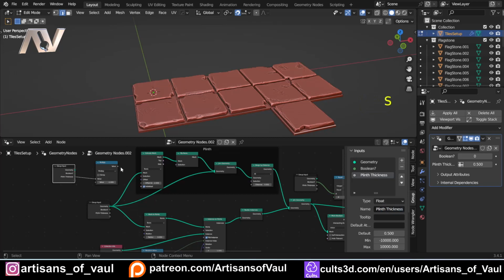So we've got that there, drag that into our offset, and at the moment it's down as 0.5. I'm going to change the default to 1, the minimum as 1. Actually, let's do 1, and then the maximum can be whatever, 5. Anything more than that's ridiculous.